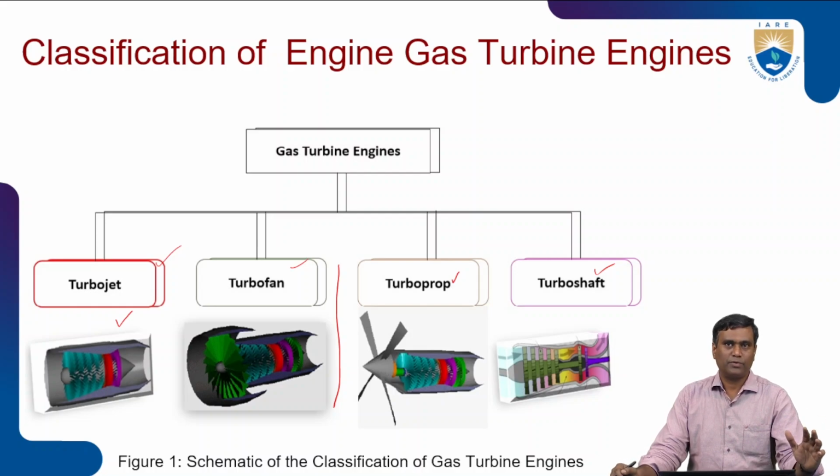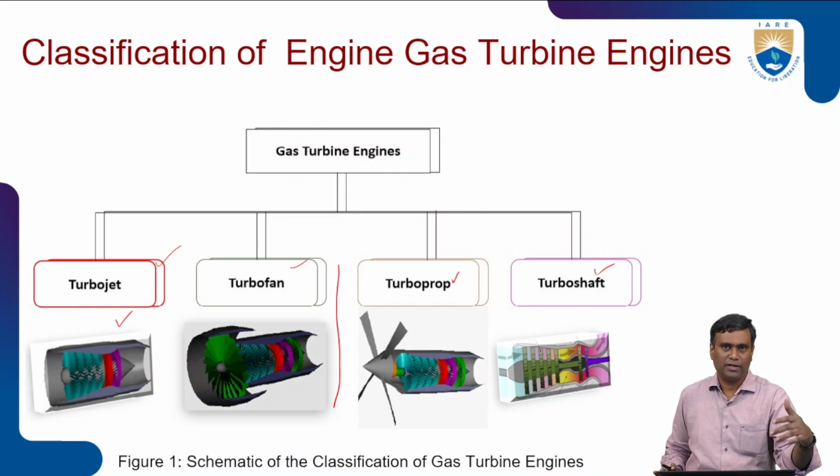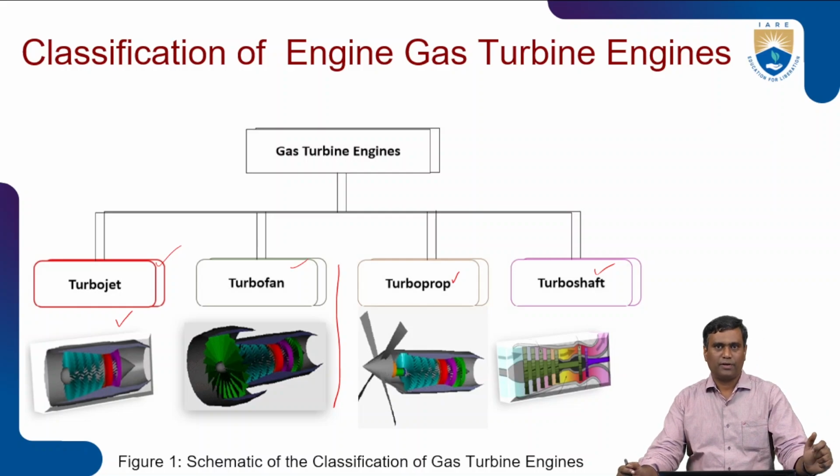When you compare with turbojet, turbofan is more fuel efficient at moderate speeds, close to Mach 0.8 or 0.85. Above that, turbojets are efficient, but turbojets consume more fuel, whereas turbofan is fuel efficient during lower transonic or lower subsonic speeds, where it is advisable. That is the reason turbofan is mostly used for airlines.